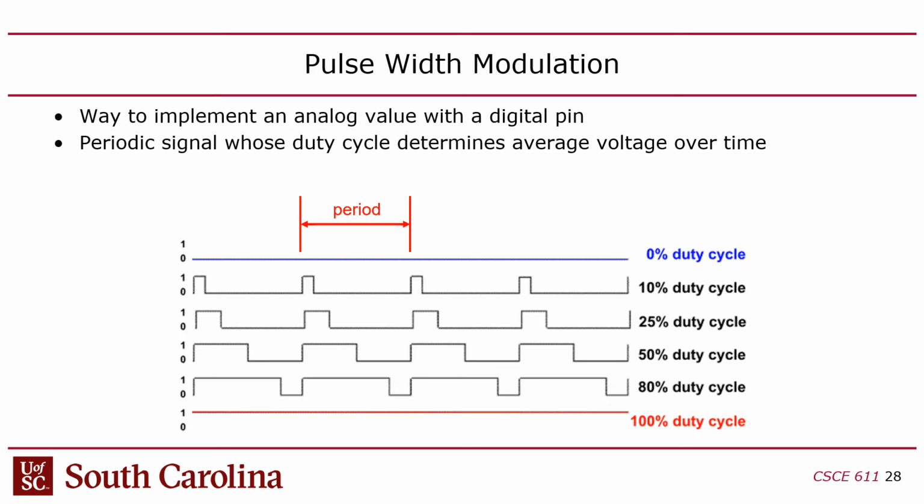That's a harder decision. So the frequency depends on the application. Generally speaking, you want the frequency to be as high as possible. Usually, if you buy an Arduino, an Atmel 328. When I say Arduino, I mean the quintessential Arduino chip, the 8-bit Arduino Atmel 328P. That has a hardware PWM circuit on it. It's part of the timer peripheral. And I think it runs at 25 kilohertz. So that's generally where you'll see a lot of PWM signals work at.